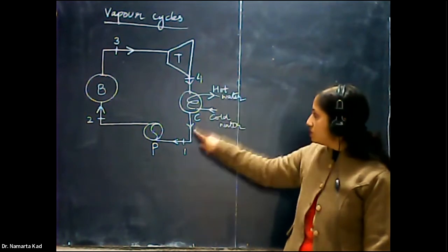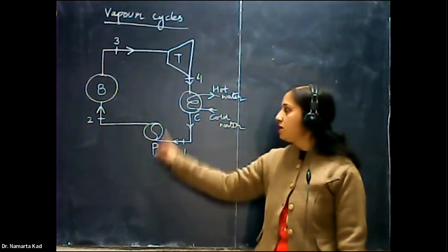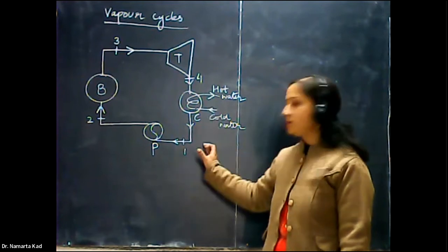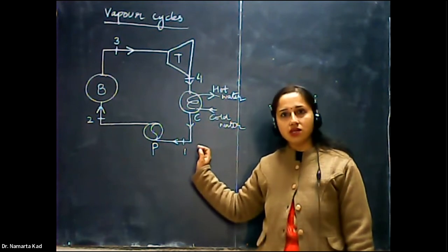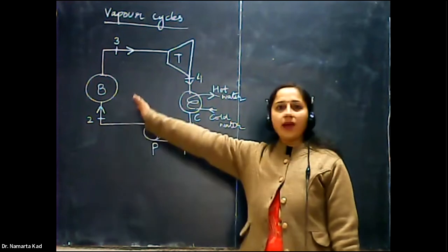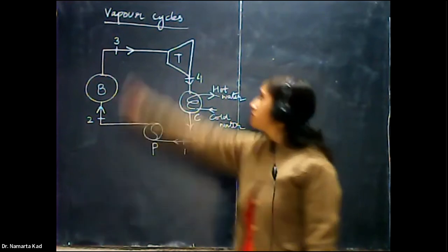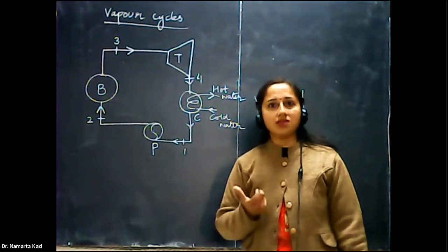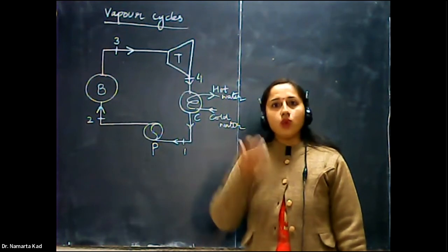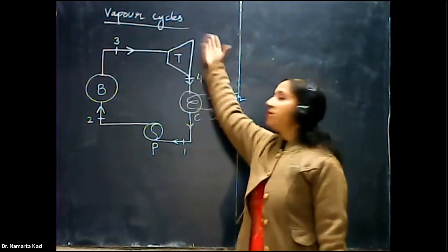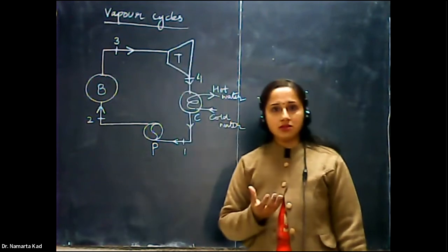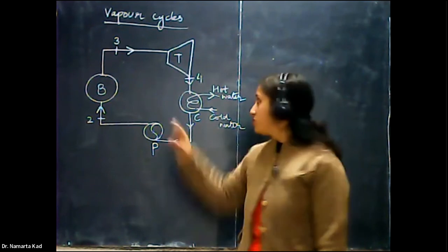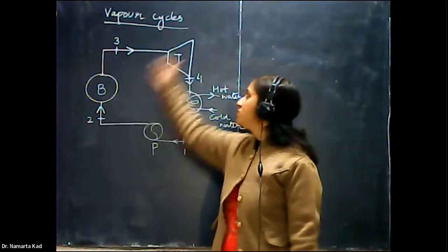Okay, and then these are the different arrows, and there is the pump. That is the feed water pump. The condensate that is taken from the condenser shell is again fed back to the boiler. So this is the complete cycle that we call a thermodynamic cycle. And why is it called a vapor cycle? Because vapor, that is steam, is the main substance in each stage.